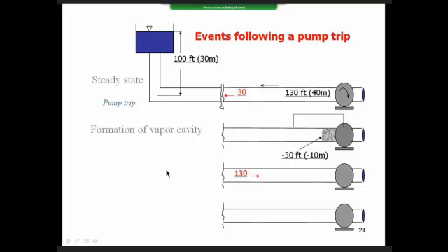Now you have this 100 feet of head, so now going in the opposite direction, you have 130 feet of head, which is collapsing the water column. Well, 130 feet of head can move a water column considerably faster than 30 feet. So if you may have 5 feet per second of velocity initially, you may have 10 feet per second of velocity at the time it collapses.